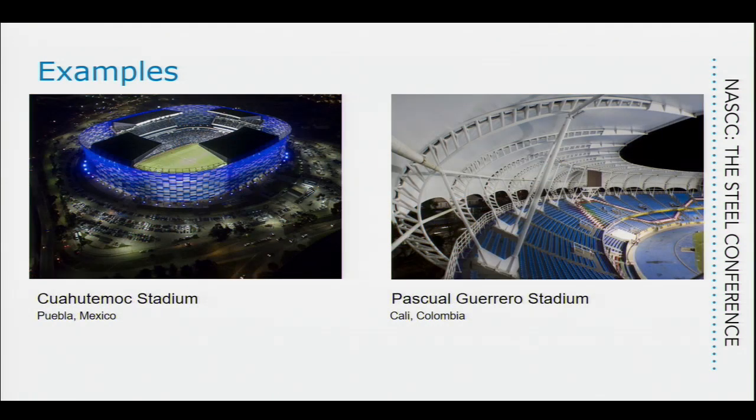And then these two are two structures that we designed in our firm. The one on the left is the Cuauhtémoc Stadium in Mexico. And what you're going to see is a lot of membrane structures are also used for facades. Okay, you'll see some examples further on of pneumatics that we use in some facades. And this stadium was an existing structure, and they wanted to kind of upgrade it and dress it up a little bit. So we put this facade of ETFE that we built as a pattern of mosaics on the outside.